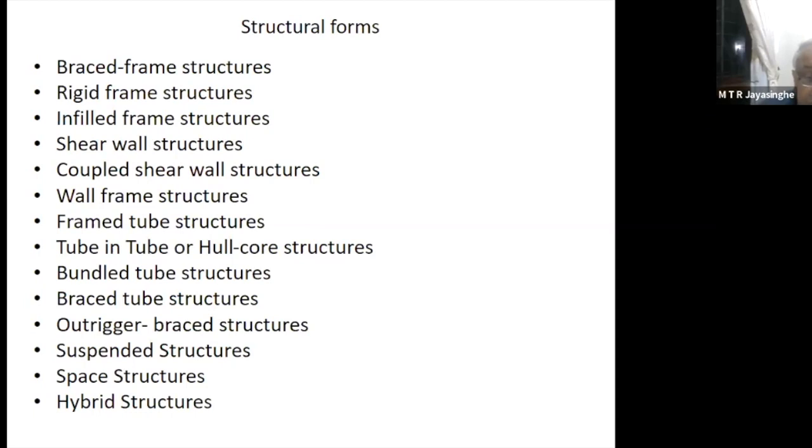Is it recommended to over-design the roof slab of a high-rise building to improve the overall lateral resistance and reduce overall deflection? It will not. There's no way you can control the deflection of a building by designing the roof slab. It's a wrong concept.